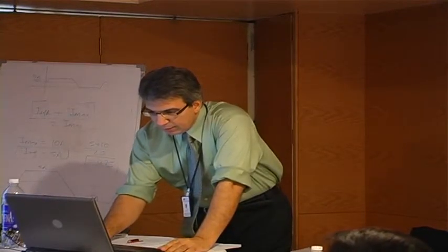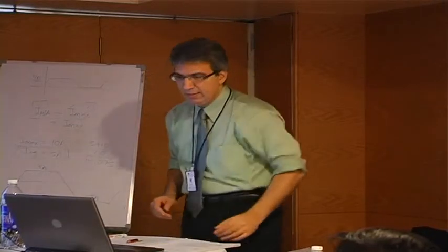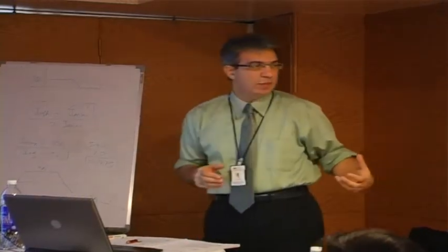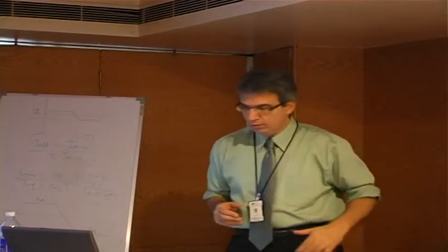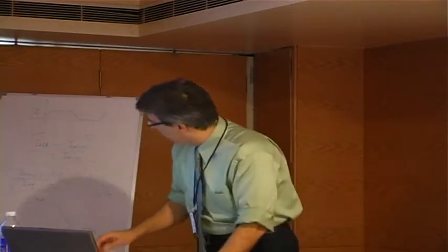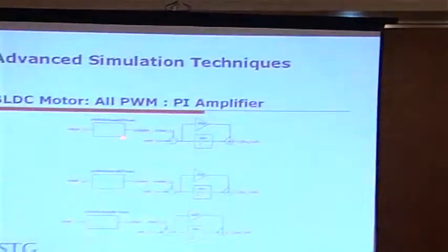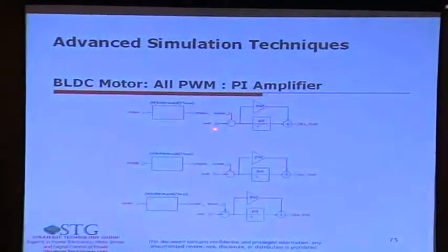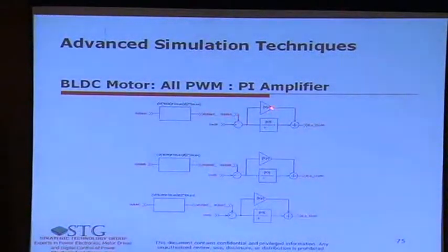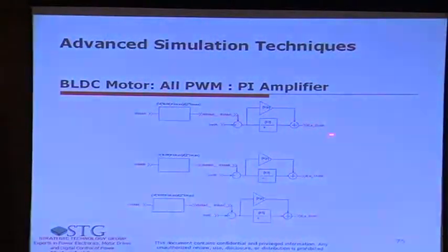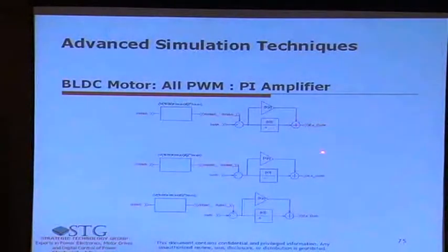And here is a simple PI loop. We basically take the feedback. Now when you take the feedback, you also normalize it, using the same formula as for the reference. So this is the feedback coming in. I reference A goes here, feedback goes here, you have a simple KP, KI loop, and that basically becomes your final duty cycle value: EA out A, EA out B, EA out C. Okay, so it simplifies things.